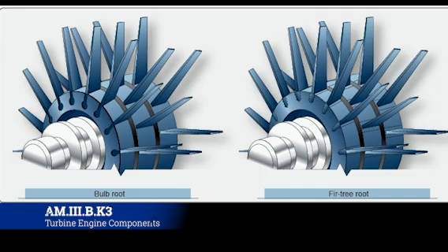The other thing that you'll have to remember is to keep the engine in balance. Like if you've ever put clothes in the washing machine and put them all on one side, the centrifugal force starts to rock the machine and makes a bunch of noise. The same thing will happen here if those blades aren't balanced appropriately. If you go out to our JT9s, you'll find that every one of those blades on the fan is balanced with another blade across the spinner with the same grams. So it'll be like 400 grams, and the other one's like 401 grams or whatever.